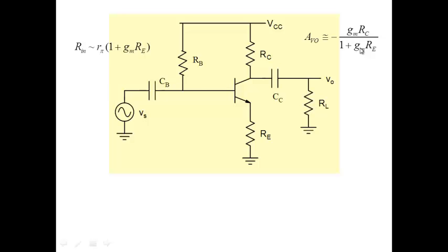Let's come back to the issue that we are talking about. I have a 20 millivolt signal, and I want to amplify it. To manage distortion, we would like to keep this voltage at 10 millivolt. Now you can see there's a natural voltage divider. The signal that I apply here, part of it will drop here and another part will drop here. So there's a natural inbuilt voltage divider in the circuit. One can show that the base emitter voltage, VBE, is equal to Vs, whatever you apply here, divided by 1 plus gmRE.